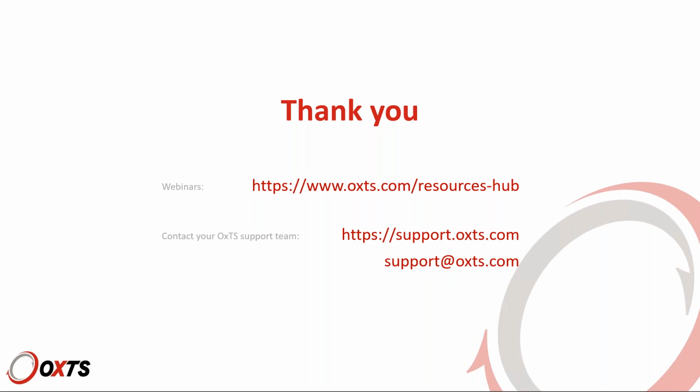Thank you. So next question. Can data be reprocessed to correct for if you have used an incorrect datum during the initial run? Yes, you can do this in post-processing by using GX/IX processing mode. So you can do that basically in post-processing. The short answer is you just need to specify the correct datum.